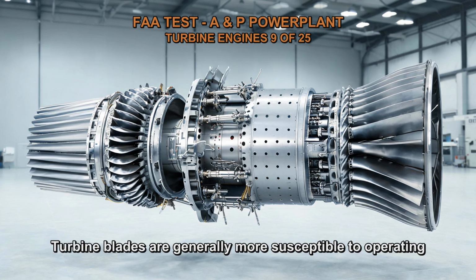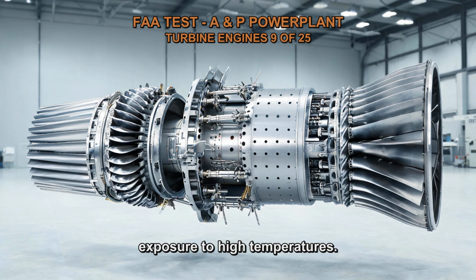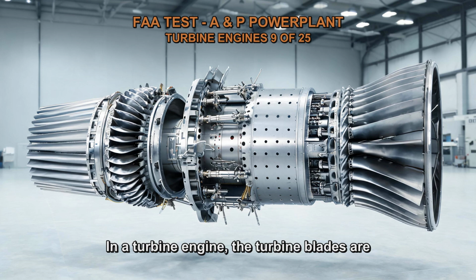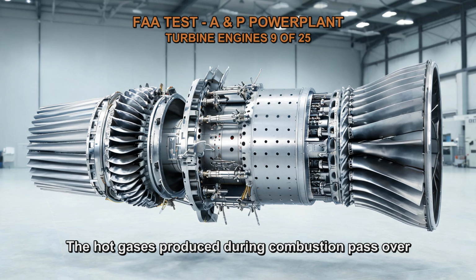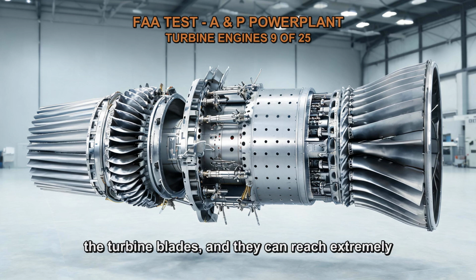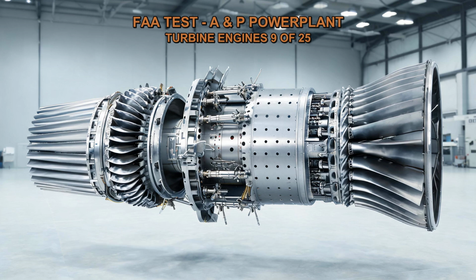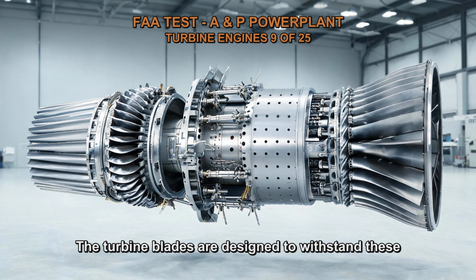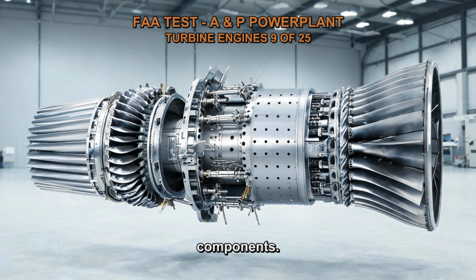Turbine blades are generally more susceptible to operating damage than compressor blades primarily because of their exposure to high temperatures. In a turbine engine, the turbine blades are located in the hot section of the engine, where they are subjected to the highest temperatures. The hot gases produced during combustion pass over the turbine blades, and they can reach extremely high temperatures due to the combustion process. The turbine blades are designed to withstand these high temperatures and extract energy from the hot gases to drive the engine's compressor and other components.